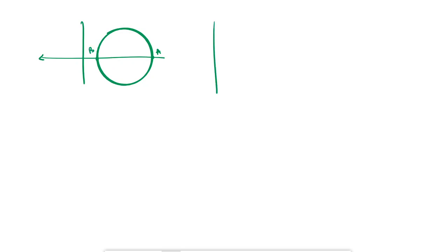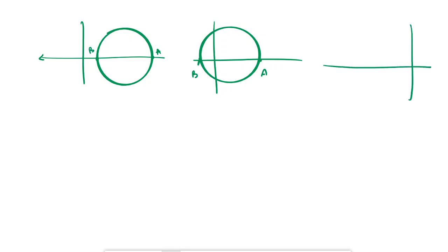So we have two ways of looking at that. In general, when you do a Mohr circle, you have 3 different cases. When both sigma A and sigma B are positive, when one of them is positive and the other one is negative, and when both are negative. And this is enough to understand what we're doing. It doesn't matter which one is A and which is B, but let's keep it consistent.